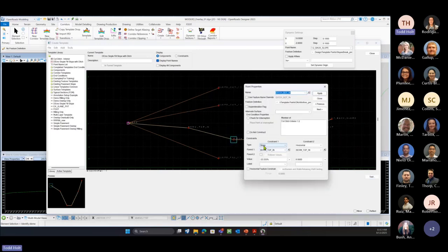And here we have another slope. So maybe that label, we want that to be a berm top, and this is our ditch bottom. We now can pick the berm slopes, but maybe that's a different label than this berm, right? So if we apply this berm slope, it's going to change both of these. So maybe this one, we need a different name.